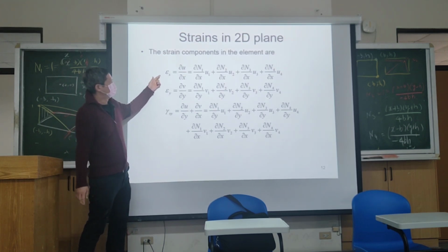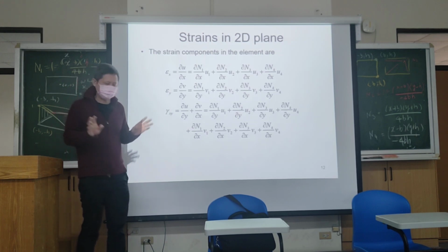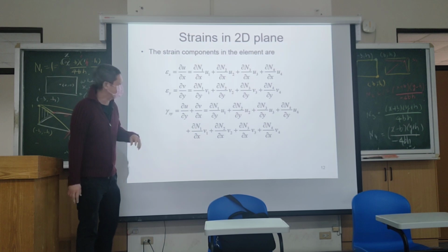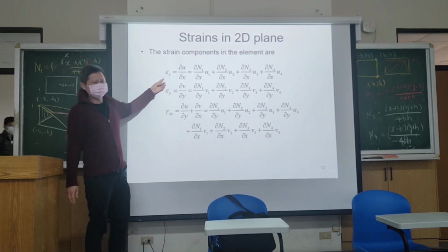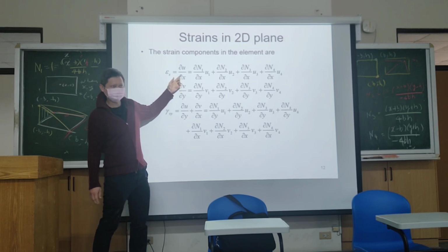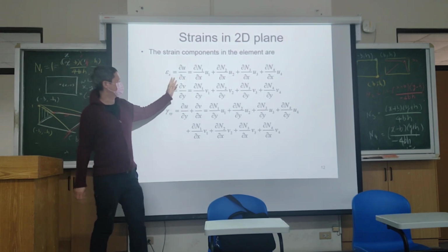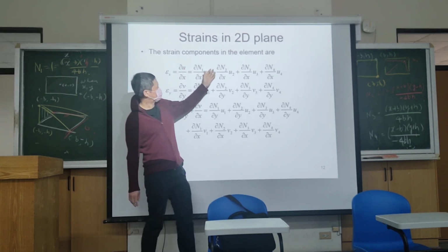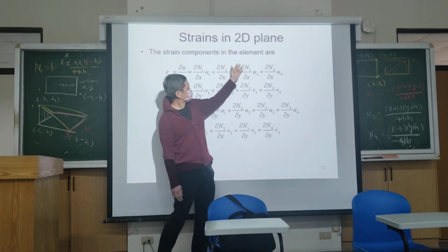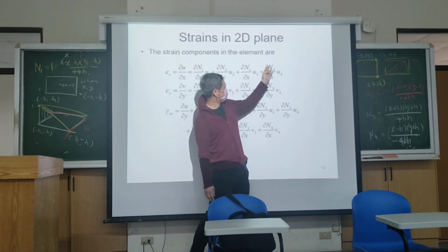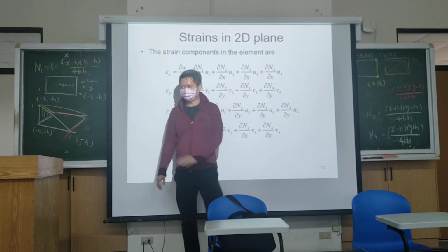strain function. Okay, here we are not using isoparametric, to avoid confusing you. We are still using the physical coordinate. The gradient in the x direction is then the derivative of the displacement with respect to the x coordinate. Then you now have del N1 del x u1 plus del N2 del x u2 plus del N3 del x u3 plus del N4 del x u4.